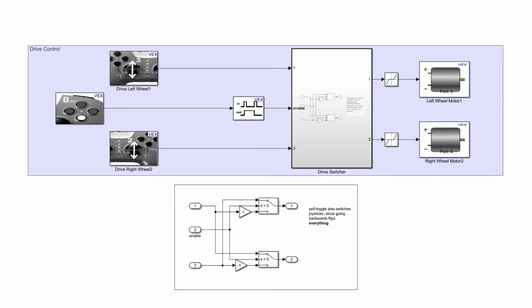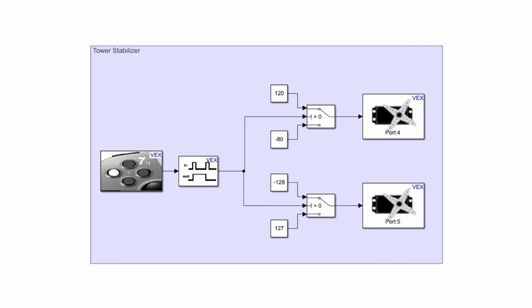We also used the two deadbands to avoid low power being sent to the motor, causing a large amount of noise with no real movement.